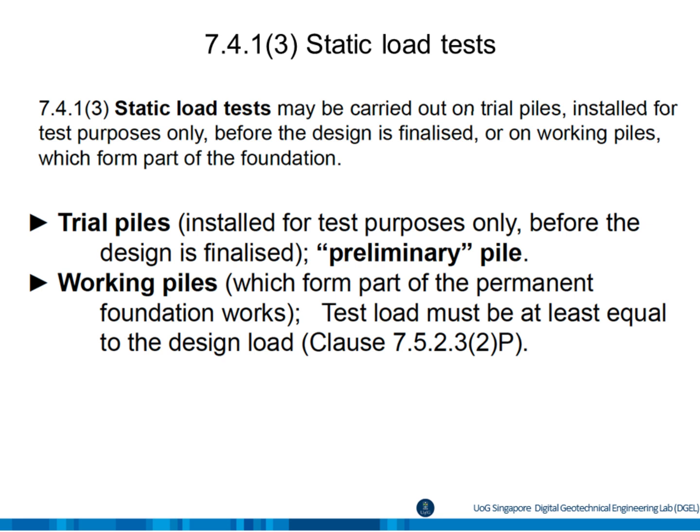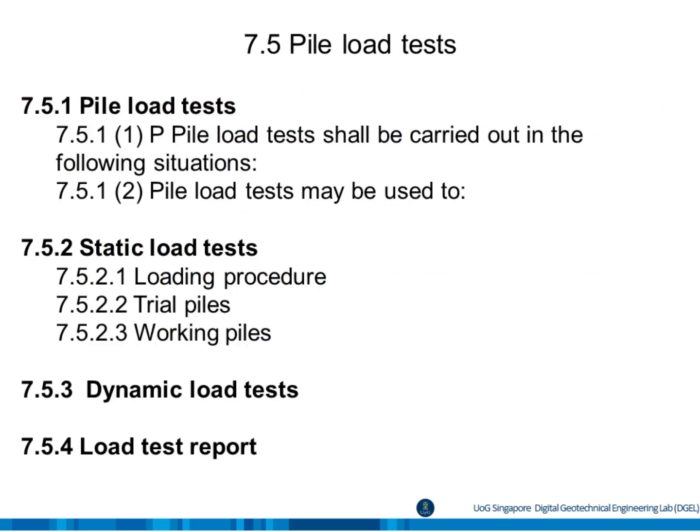For trial piles, a thorough site investigation is essential to understand the soil conditions around the shaft and beneath the base. Working piles, on the other hand, are part of the permanent foundation. They must be tested to at least the design load. Clause 7.5 describes pile load tests. It covers static load tests, dynamic load tests, the testing procedures, and also the required format of the load test